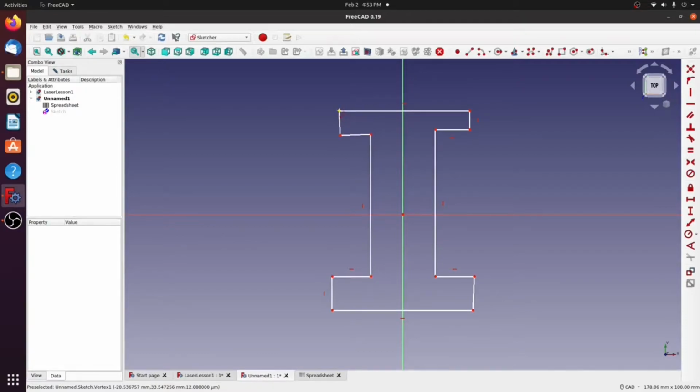The main point here that we're trying to do is just to create the right number of lines and points. And then we're not going to try and eyeball this thing. We're going to go in and specify every detail here. This is very, very important in CAD modeling. So I hit the escape key to exit out of that tool. Now I'm back to the pointer. And I can begin applying constraints.